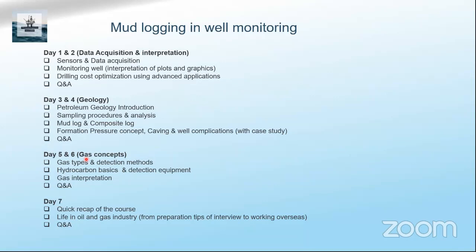When you say gas, from the safety point of view there is CO2, carbon dioxide, and H2S. These two are detected with the help of sensors, and then the hydrocarbons are detected with the gas panels, the gas detectors. I'll go through the types of detectors, what factors we have to look into for QC, what care is to be taken, and how they help us in drilling safely and in formation evaluation.